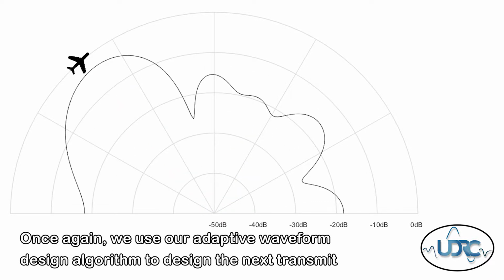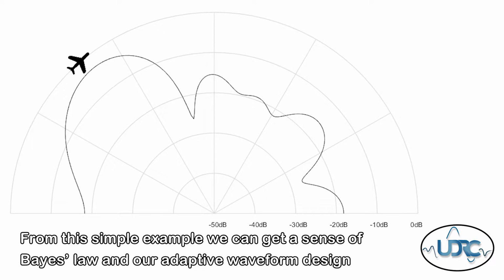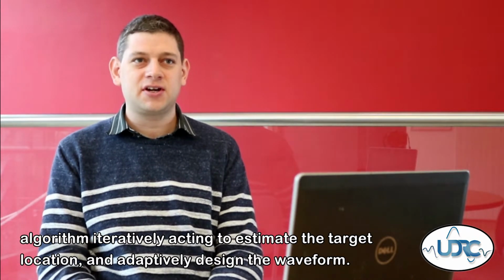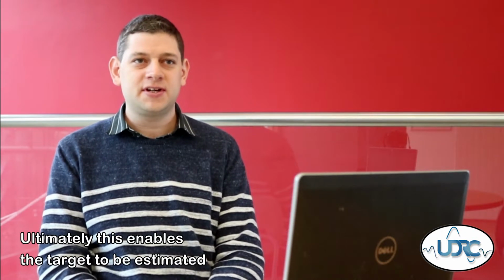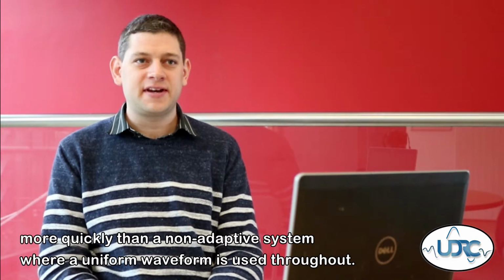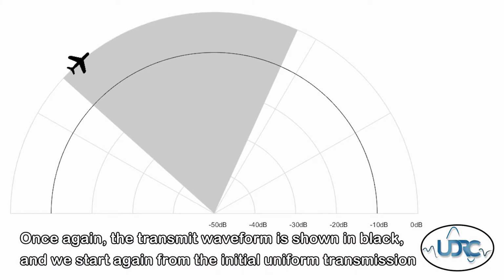Once again, we use our adaptive waveform design algorithm to design the next transmit waveform given the estimation. From this simple example, we can get a sense of Bayes' law and our adaptive waveform design algorithm iteratively acting to estimate the target location and adaptively design the waveform. Ultimately, this enables the target to be estimated more quickly than a non-adaptive system where a uniform waveform is used throughout. Once again, the transmit waveform is shown in black, and we start again from the initial uniform transmission.